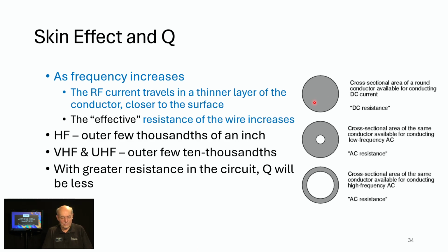So for DC, you've got heavy battery cables for a lot of current. At higher frequencies, VHF, UHF, and above, if you could imagine a monofilament fishing line that was painted with conductive paint, that would be an effective conductor, because the section where the monofilament fishing line is wouldn't conduct anything anyway because of skin effect.